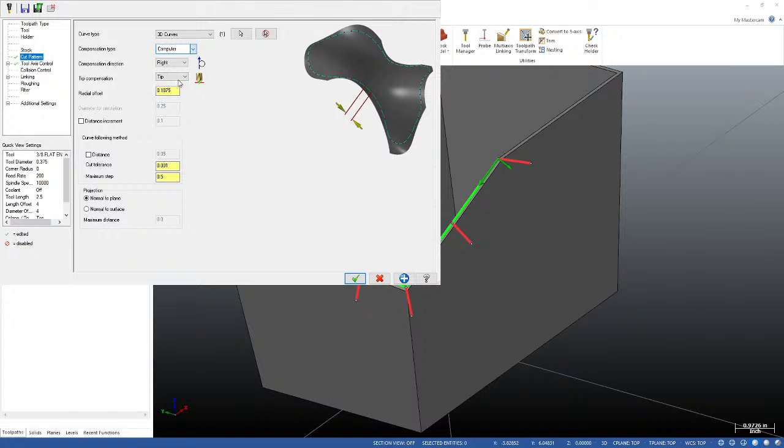The default generic 5-axis mill is not. Now, sometimes you can end up using 2D compensation, G41 or G42, if you have a table style machine. But you're really going to have to work with your post-processor vendor or make the edits yourself to get that to happen. Right now I'm just going to leave it set to computer.